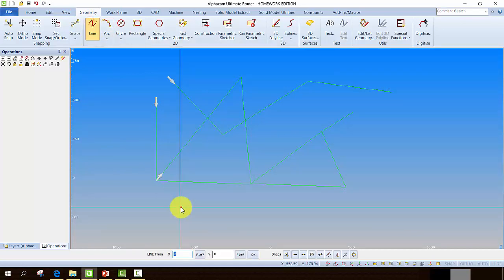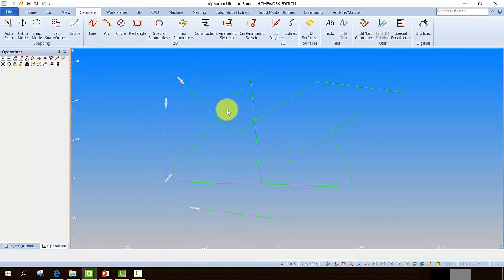You've probably noticed those white arrows at this point. Those white arrows are going to be very important to us because they will help us to determine which of these green geometries are useful and can have toolpaths assigned beside them. So if you use the shortcut command Control and G, you can turn those ghost tools on and off. Most of the time we will want them on, but for now let's turn them off with a Control G just so they don't get confusing.